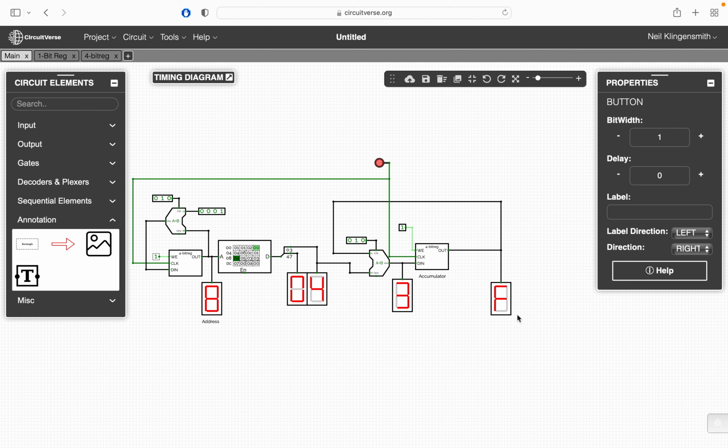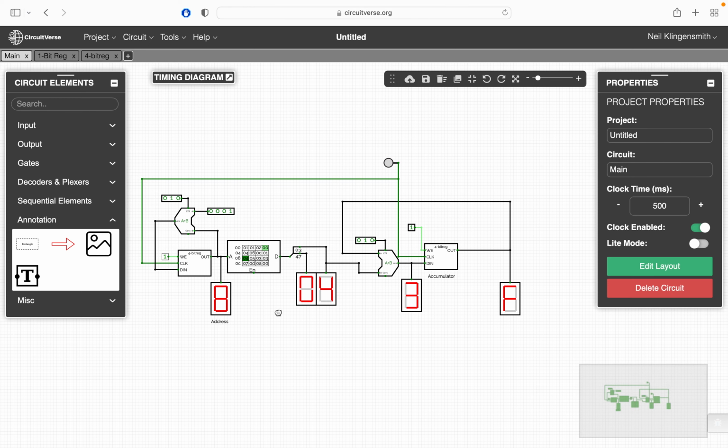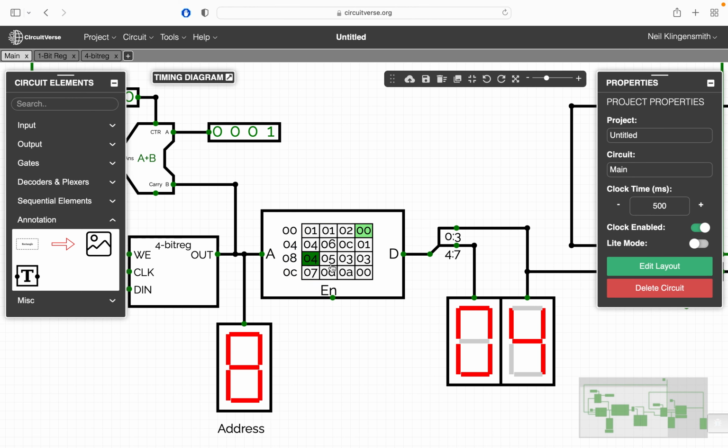Okay. So this is basically the beginnings of a simple computer. Okay. So what you can see we have here is a memory. This is a memory that contains all of the instructions, right? So this computer really only has one instruction. It's an add instruction. It just tells us to add a 4-bit number to the accumulator. Okay, we could define other instructions, of course, if we wanted to. Maybe I'll make some videos about how to do that. But basically, it's a very simple computer, but we can write this, and the sequence of these instructions that we program into this memory, this is called the program, right?